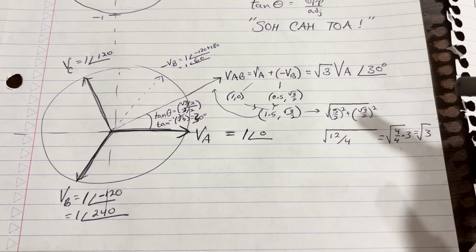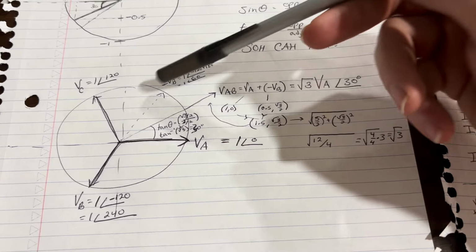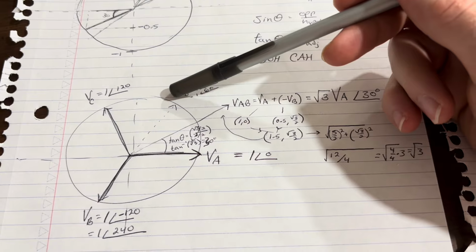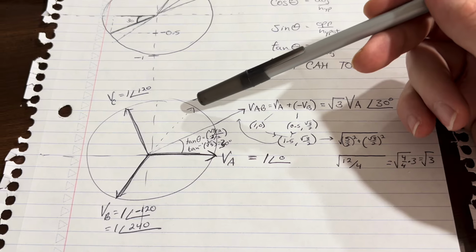Now, positive sequence voltage phasors. Quite a jump from high school math. But if you picture you're standing right here, as these phases spin in time, you'll get slapped in the head, A, B, C, in that order. That's why it's positive sequence.